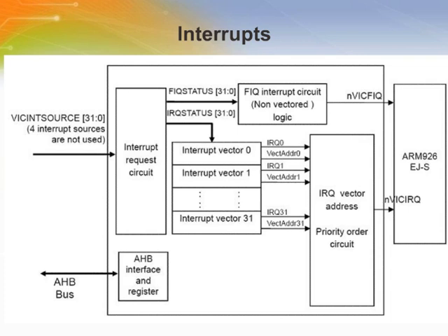They support 28 interrupt sources, assign 32 levels of fixed hardware priorities to the interrupt sources, to be used if multiple interrupt requests of the same software priority level are made simultaneously, enable setting 16 levels of software interrupt priority for each interrupt source, enable masking hardware and software priority levels, support two types of interrupt requests, normal interrupt request IRQ and fast interrupt request FIQ, and enable generating software interrupts.